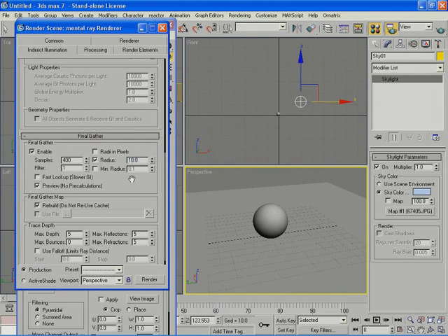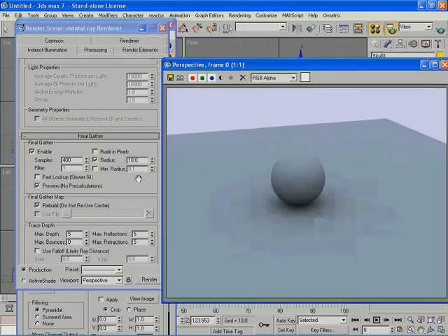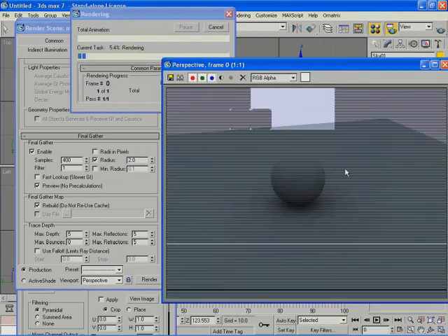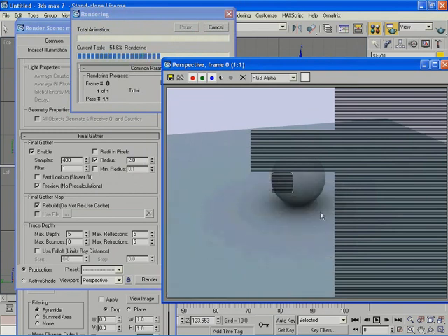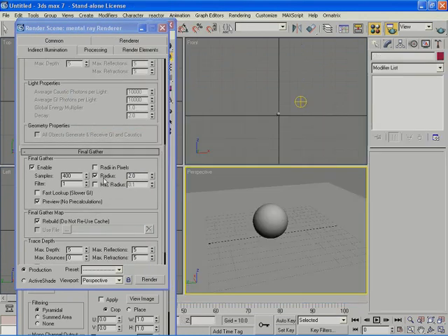So I'm going to render now. Now with the size of 10, I still get big chunks of occlusion. If I go to 2 and render, I'm going to have smaller chunks, and therefore my rendering is going to be much better. We can activate 1 radius, or we can choose to have 2 radii, the minimum and the maximum. Now, the maximum radius is the size of the biggest splotch of occlusion that we can have, and the minimum radius is the size of the smallest splotch of occlusion that we can have. What I'm talking about is these. So if we zoom over, we're going to see that we have splotches here. Now, the smaller the radius, the more these splotches will turn into grain. And to remove them altogether, I have to uncheck preview.